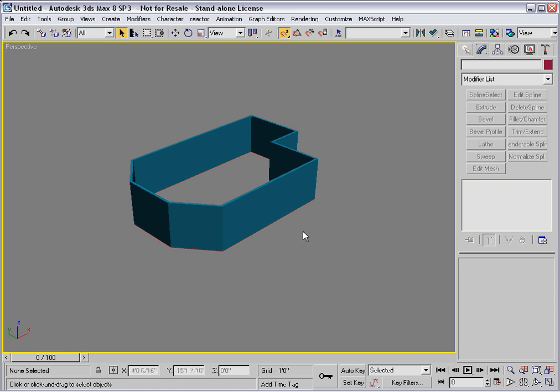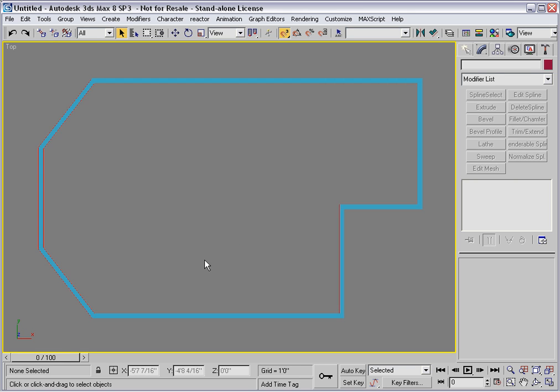If you choose to extrude solid walls without leaving gaps, you'll have to cut openings in those walls, and I'll show you how to do that now. I'll go back into the top viewport in wireframe mode. Let's focus on creating an opening here for this door.